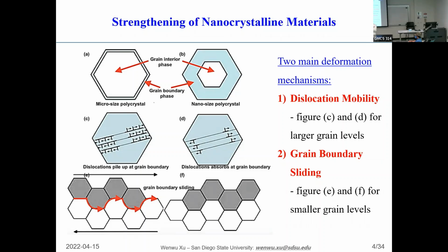But once the metal goes into the plastic range, which means permanent deformation of a piece of metal, a very important type of defect, the so-called dislocation, is going to come in. Once the dislocation is generated, it will keep generating with increasing plastic deformation.